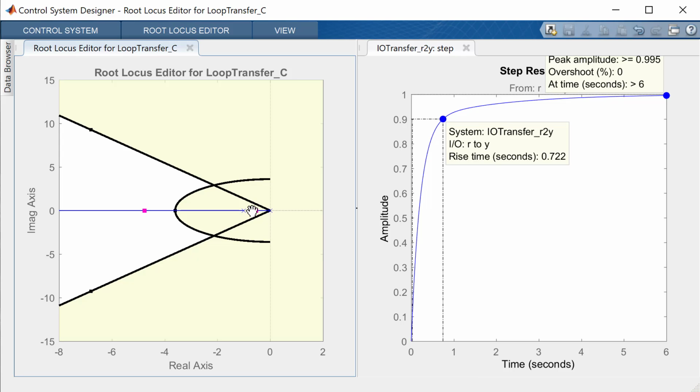And so this shows that it's probably a bad idea to place our poles like this. We do see that we get some interesting behavior here. Here we're getting an overshoot that is very small, and your rise time is actually rather short, still outside of our time domain specification that we want. But it also has this long-term behavior, it takes a full 5, maybe 6 seconds for it to actually get there. So we'd like something to happen faster.